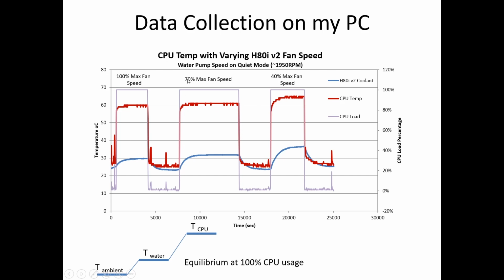So now we switch the processor on at 100% by using one of these burn-in pieces of software, and the temperature again converges to a figure now a little bit above 60 degrees, 62 degrees or whatever it is. That's where it tends to sit. And in fact you see that the water temperature is actually a little bit higher as well. I would say that the difference between that water temperature here and here is greater than the difference between that and that, very slightly.